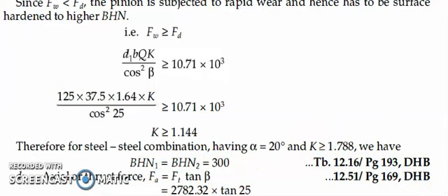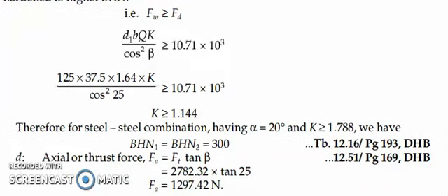And next the axial thrust, that is another section given in the question. Axial thrust, or we can denote it as Fa, is equal to Ft into tan beta. So we need only beta here, and that is directly given in the question. That equation is already shown in the textbook, that is 12.51. Using this equation we can find the value of Fa also.